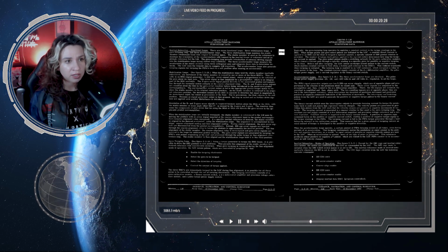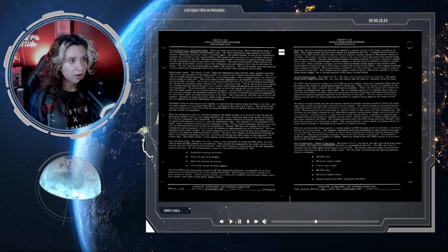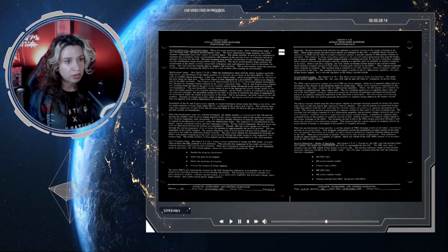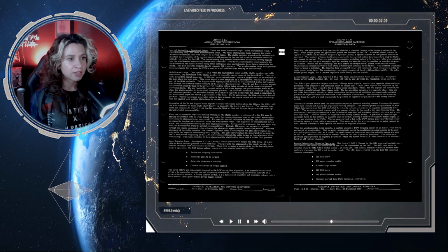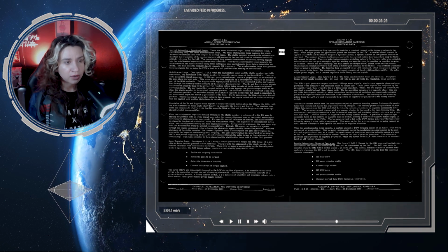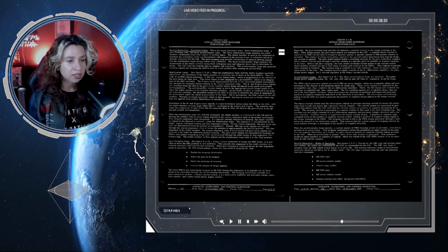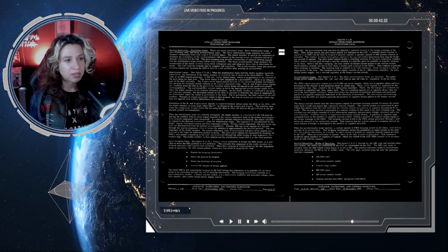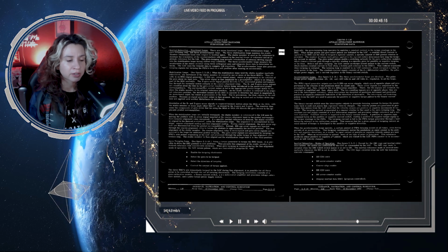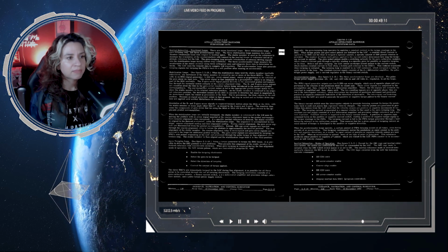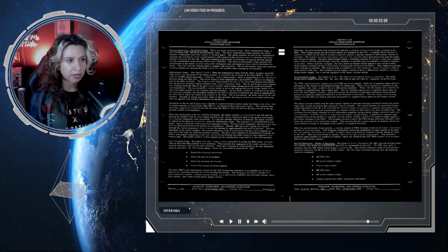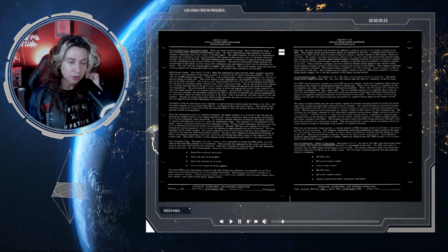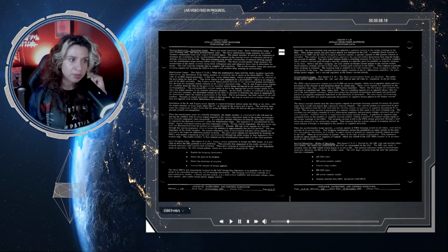The 2 resultant signals are of opposite phase. They are fed to the interrogator circuitry, which determines the direction of pendulum movement and generates positive or negative commands indicative of the direction of movement. The interrogator and switching pulses from the LGC are used to generate the positive or negative torque pulses from the binary current switch. The binary current switch uses the interrogator outputs to generate torquing current to torque the pendulum back to null, and pulses that represent velocity changes.